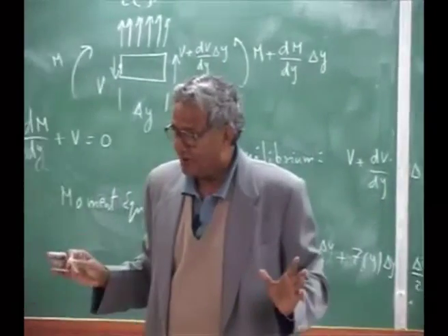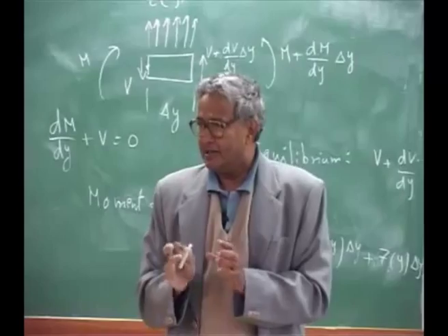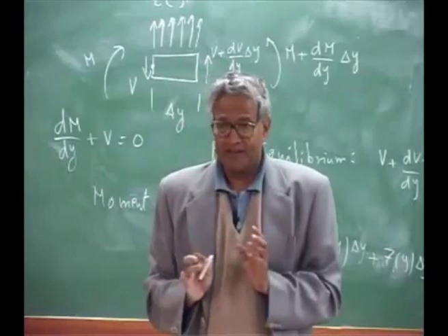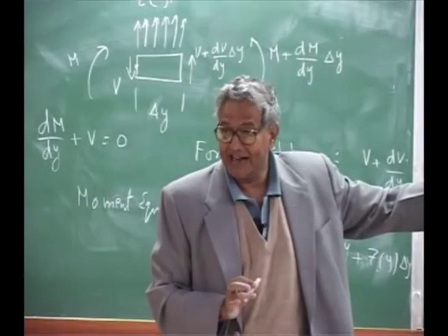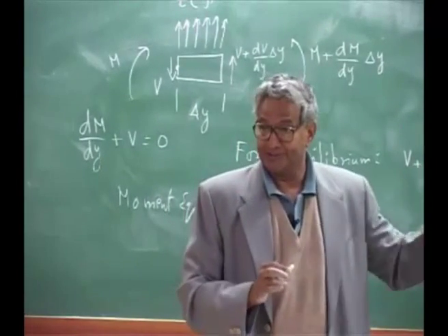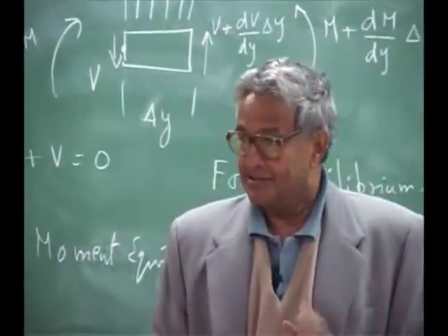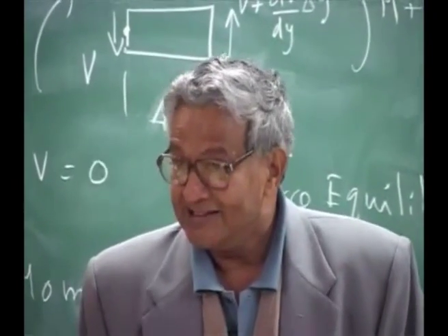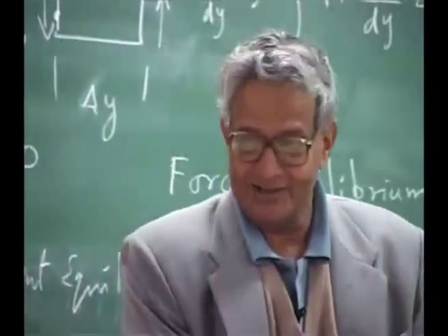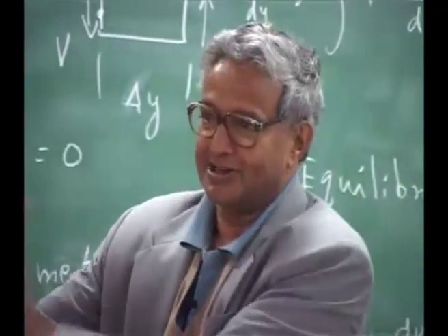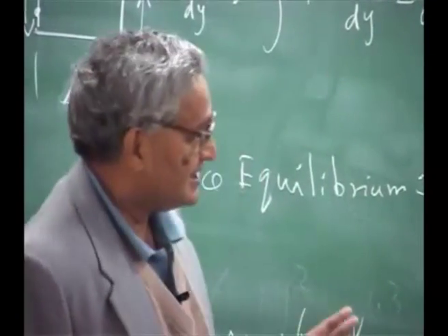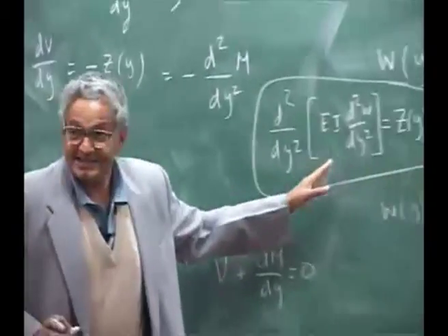So all your aeroelastic problems, sometimes people write it in operator form. W is the deformation. Loading is Z. I have a structural operator acting on W. I have an inertia operator acting on W. Z is external load, which is the aerodynamic load, which is again dependent on W. So structural operator, inertia operator, aerodynamic operator. They just mathematically represent it in that form. Okay, is this clear? This is the differential equation form.